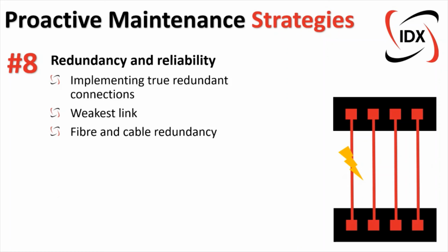Another point on redundancy and reliability is when implementing redundant systems, ensure that you fully understand how the redundant system should be implemented, understand the architecture behind it, and how devices are to be set up. It's very often that I have attended unnecessary breakdowns because a redundant system did not just fail to provide redundancy, but actually caused the failure on the network.